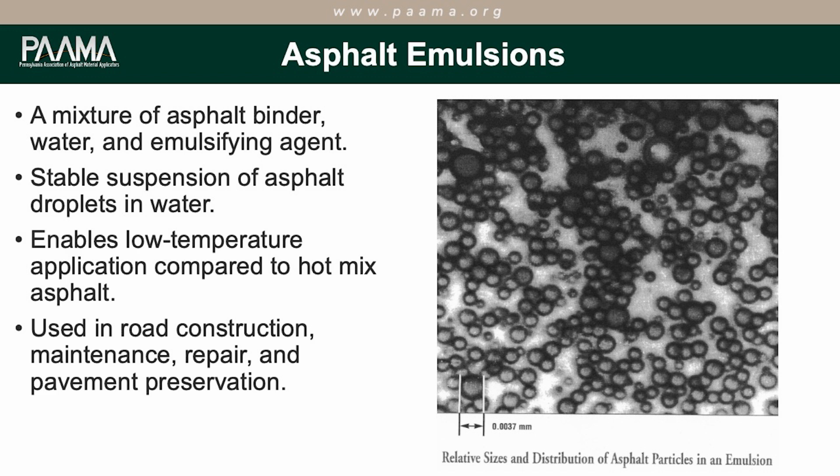You need the stable suspension of asphalt droplets in water, and all of this enables low temperature application compared to hot mix asphalt. It's used in road construction, maintenance, repair, and pavement preservation. And in the slide here, we just have a sample of asphalt emulsion under a microscope showing nice even particle sizes, which indicate a nice stable emulsion.